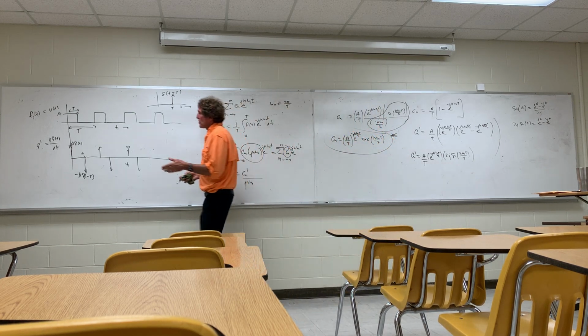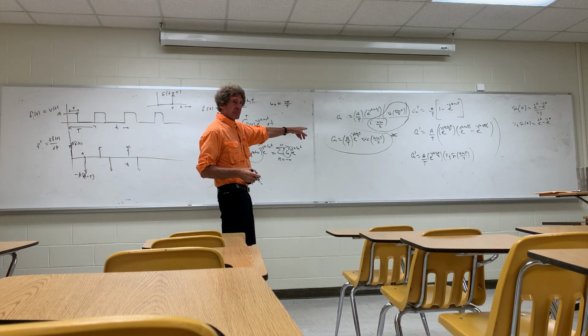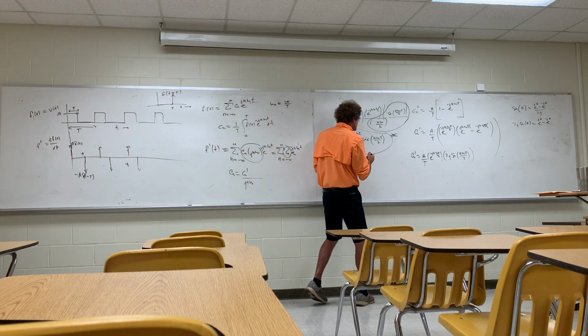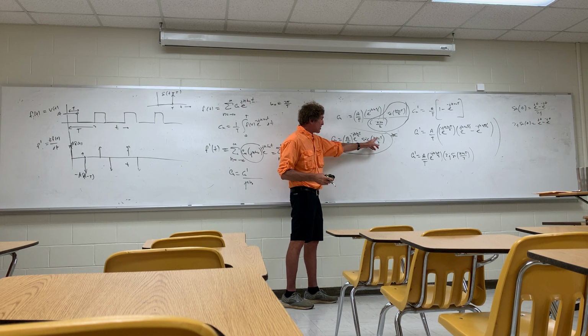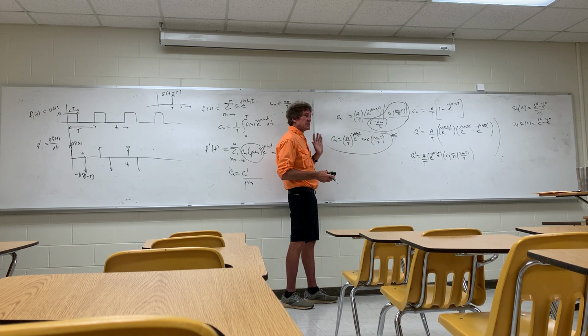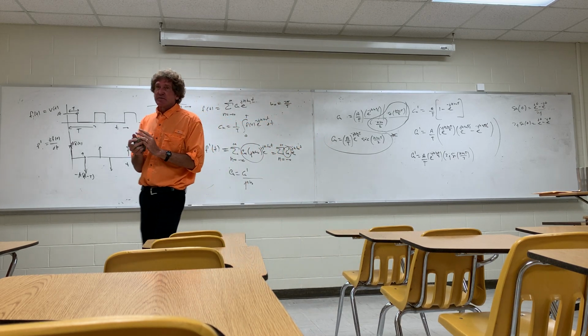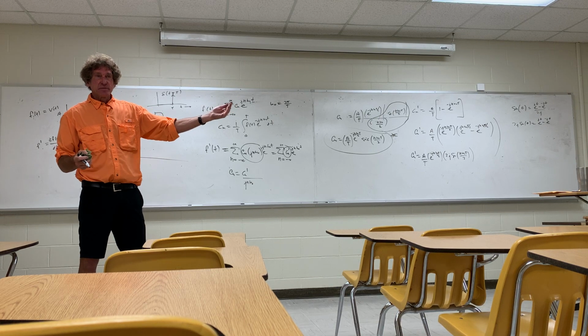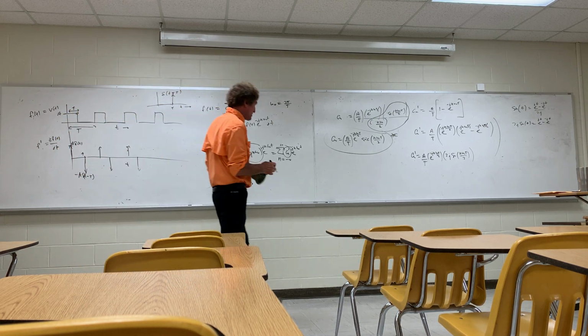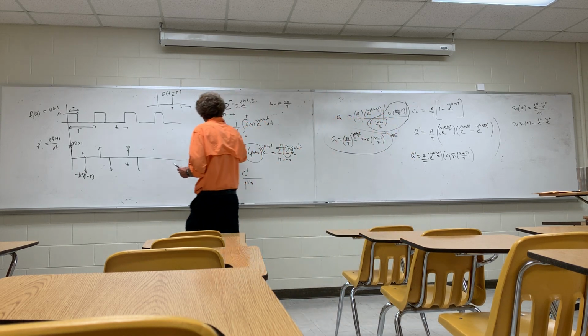So now I've got the coefficients of this infinite series versus frequency, or versus the actual harmonic level. Remember, omega naught is called the harmonic frequency, first harmonic or fundamental frequency. N times omega naught, for any harmonic, you can see the value of C of n, and that tells me the amount of signal strength at each of those frequencies in the frequency spectrum. Now I'm just going to show you something, because I'm getting close to the amount of time. I'm going to do it here.